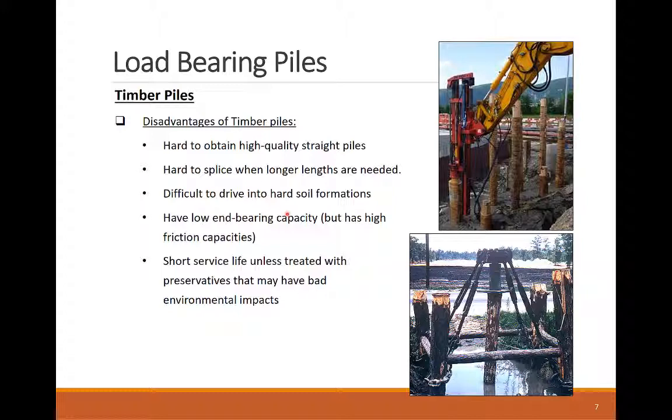Also, timber doesn't have capacity to drive in tough soil formation. This is also why their capacity comes from soil friction, not from soil bearing at the pile toe end. Finally, timber piles deteriorate faster than other manufactured piles unless they are treated with preservatives that are not that environmentally friendly.